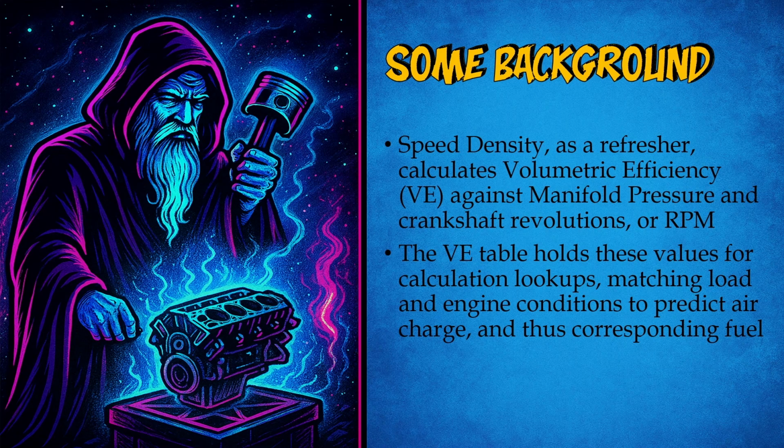And so the engine says, okay, now I know what the mass air is going to be. Fantastic. And so with that, I also then know fuel, because I have fueling tables that'll match. When I came to this generation and tuning as of late, volumetric efficiency was a little new to me. I didn't have to play around with it as much in previous areas. Mazda Speeds in particular didn't really use these tables, but they did use three-dimensional fuel command tables, which you would then measure fuel trims against, right? And that's how you would correct your airflow model.